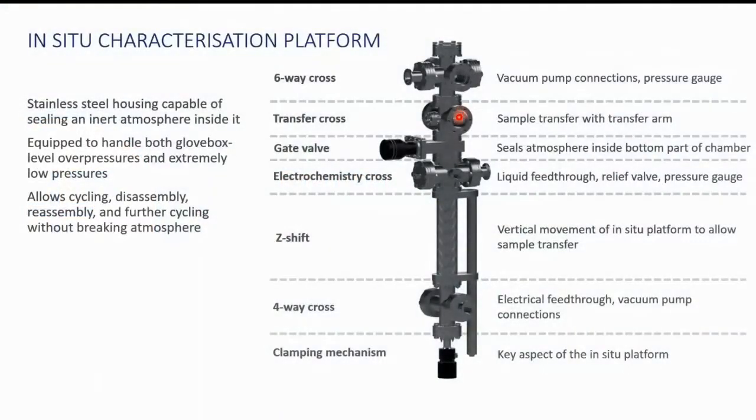The chamber is comprised of stainless steel subchambers all bolted together. The stainless steel housing is capable of sealing an inert atmosphere, both argon gas at glove box level overpressures and the extremely low pressures required by the techniques we're using to characterize our battery components.